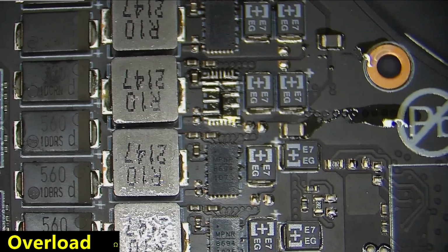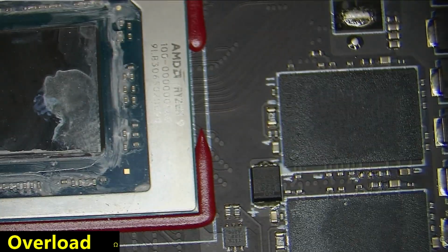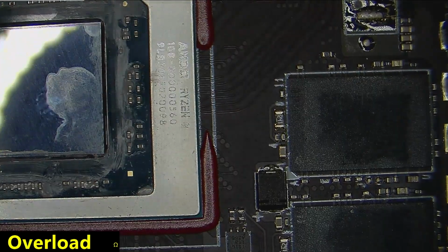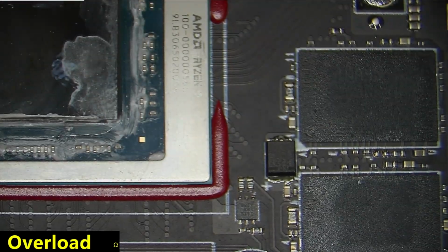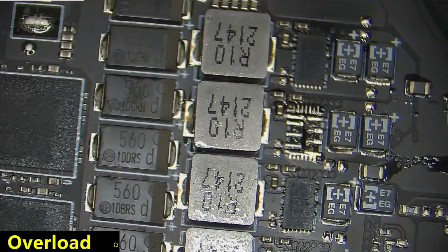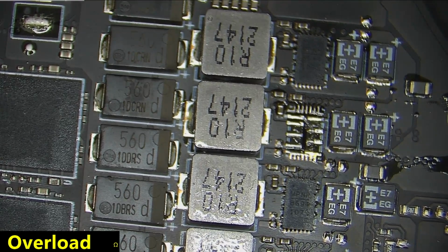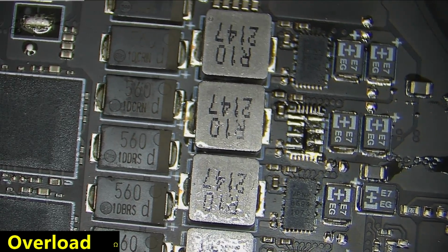It's probably what happened is just 20 volts shorted into this and screwed something up, basically. The AMD CPUs seem to survive this. I almost never see the Intel ones survive. They just die when this sort of issue happens. High side short. They don't live to compute again.